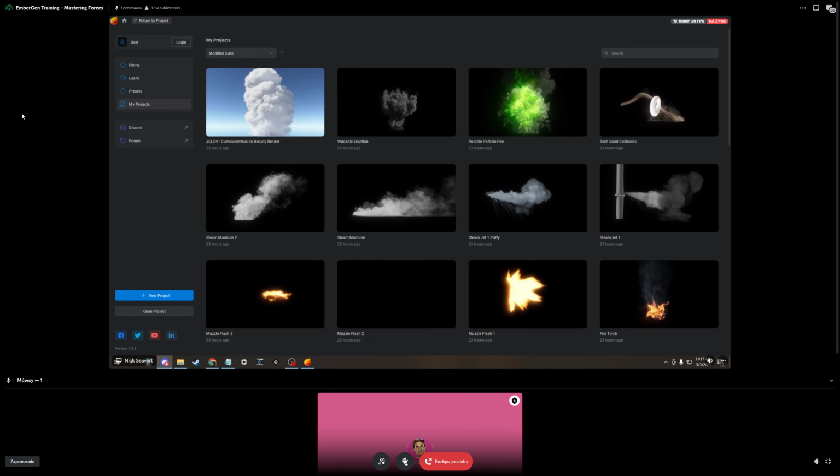And what we can do if we want it to be more detailed, and we can turn off our visualizer for just a second. If we go to vorticity, that's basically going to kind of multiply against our smoke. And nothing's happening right now because we turned our masking off. So in this case, we can make vorticity say only on our velocity channel. We can make vorticity happen only where temperature is. We can make vorticity happen only where smoke is, and so on and so forth. And it's based on the strength of the smoke and how much density there is.